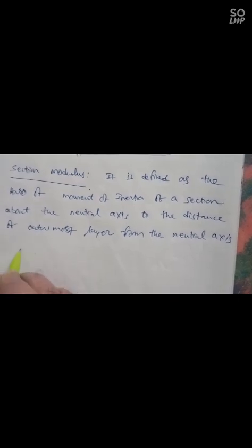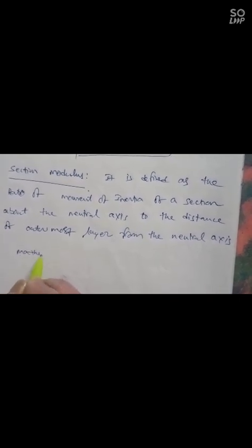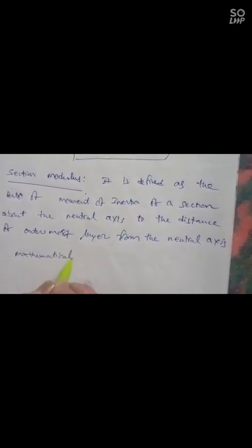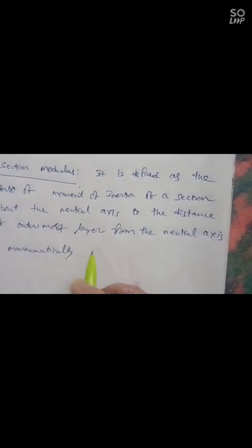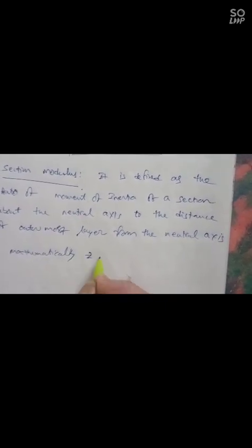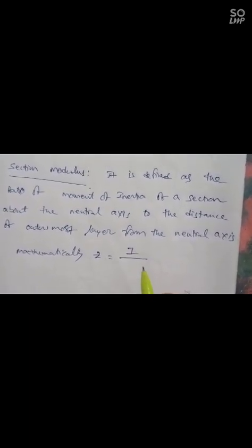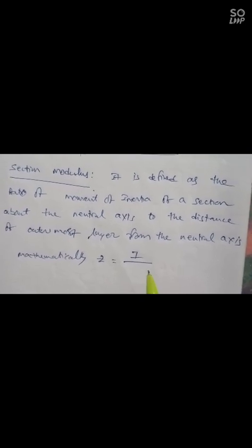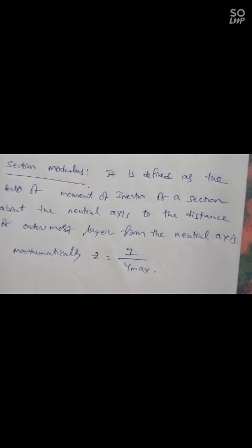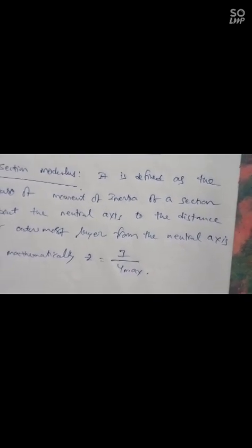Okay, so mathematically the section modulus is denoted as Z, which is equal to I, moment of inertia, upon y maximum. Z equal to I by y maximum.